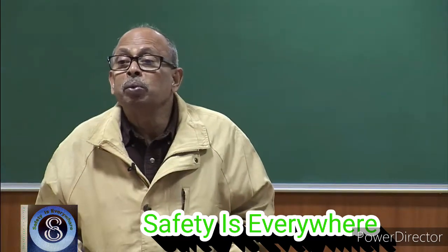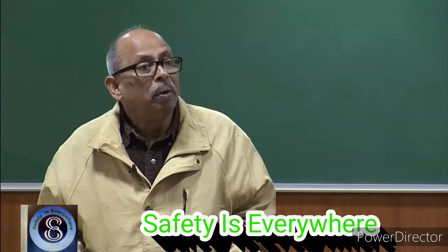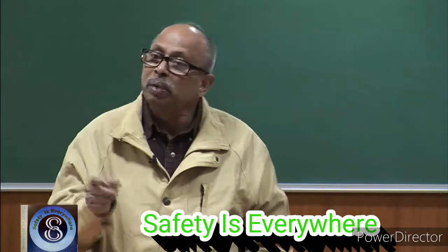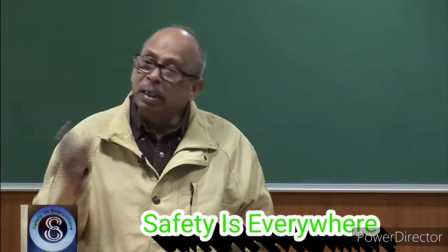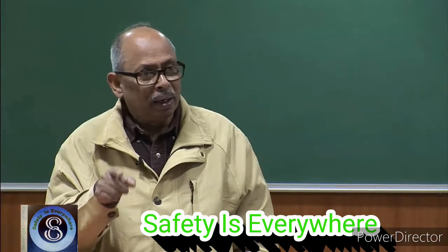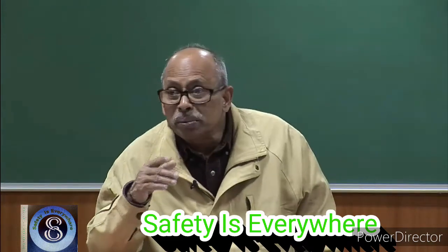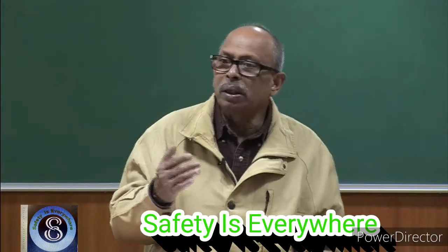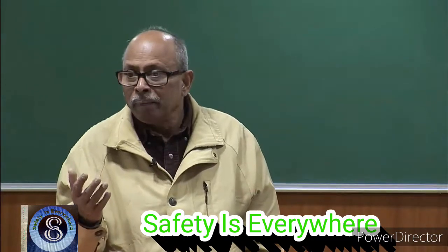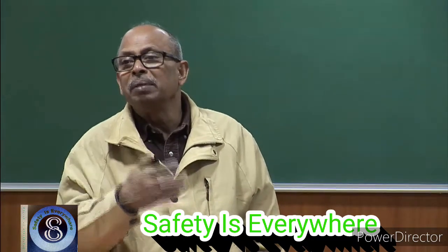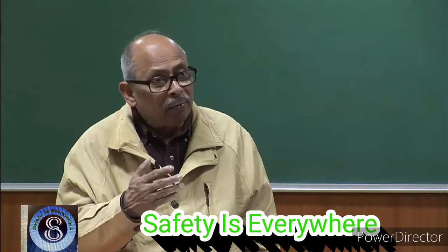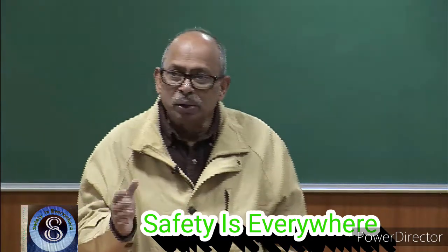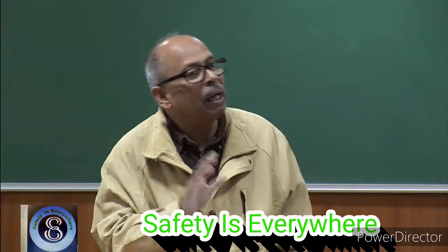But performance against what fire? Because the fire that will be there in a given room will depend upon the fuel condition of that room and the ventilation condition of that room, right. So, it is space dependent, it is not independent of the space. You cannot say that if I have a residential building, all residential buildings will have a similar kind of fire. Now, how do we define fire? We said by the time temperature curve. So, the time temperature curves of all the spaces are unlikely to be the same.